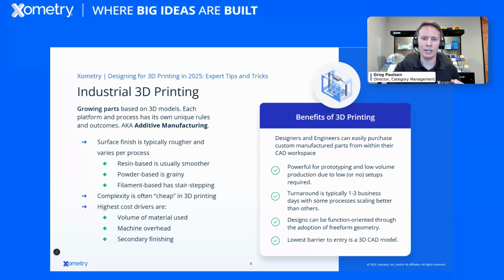With additive manufacturing, a part design, a 3D model, is interpreted in build software, often called slicing software because it's layer by layer. And it looks at how it'll gradually grow those parts using a base material in a controlled setting. Those materials can be something like a liquid resin. So stereolithography is a great example for that, and usually have kind of liquid resin, smoother look to it. It could be powder bed. So think like a flour fine powder for plastics or metals to grow parts, typically using lasers or some heat process. And then filament base.